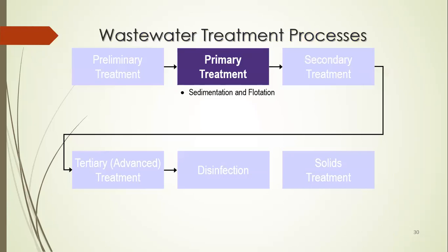As treatment techniques, you can have sedimentation tanks, that is, you tend to settle the particles, providing still conditions in the treatment basins, right? So that is vertically downward settling principles. And also you can use the principles of flotation, that is, you are taking all the waste onto the top by providing air flotation.